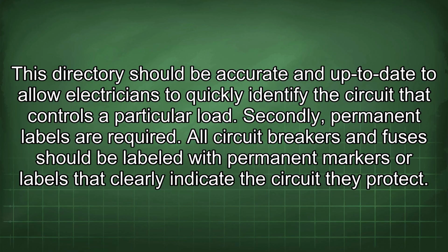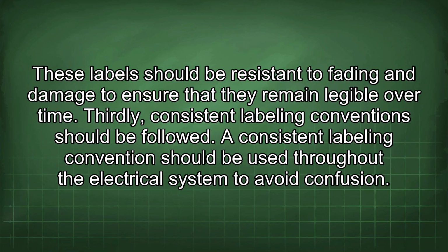Secondly, permanent labels are required. All circuit breakers and fuses should be labeled with permanent markers or labels that clearly indicate the circuit they protect. These labels should be resistant to fading and damage to ensure that they remain legible over time.